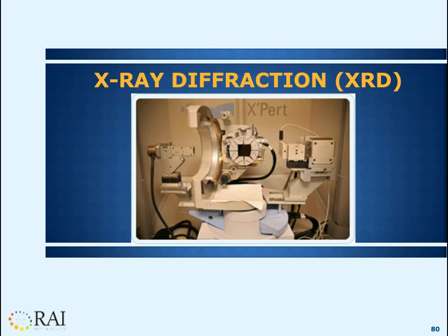It provides information on structures, phases, preferred crystalline orientations in materials, average grain size, crystallinity, and crystal defects in a material. So this is very, very helpful in determining why materials might have fractured in grain boundaries and other locations. Helps also determine if you get brittle fracture or ductile fracture, which can help explain the failure mechanisms of materials as they fail.